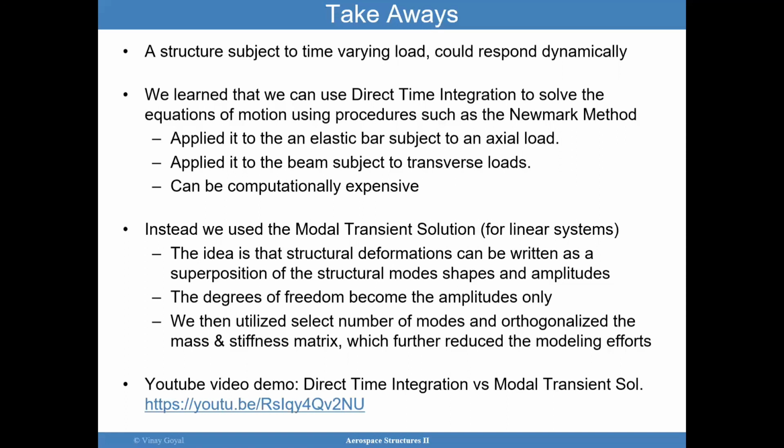And the idea here is that the whole aircraft deformation is going to really depend on the fundamental dynamics of that aircraft. And if I'm able to determine what are the frequencies and mode shapes of the aircraft, then perhaps the structural deformations over time really depend on the linear superposition of these mode shapes.